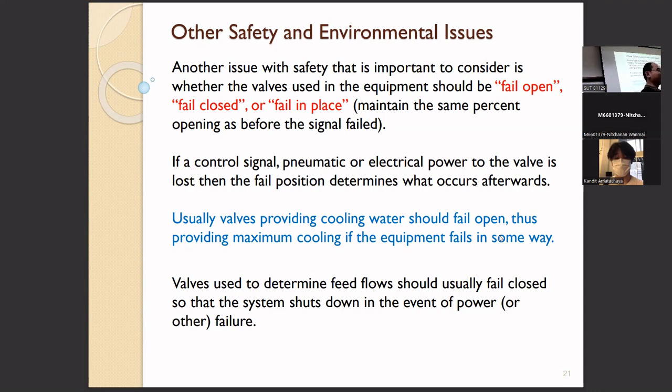It's very important. If you work with gas and you have a reactor or vessel, a closed system, in the closed system a lot of gas is at high pressure. If the pressure is higher than the limit or the capacity of your equipment, there may be an explosion based on the high pressure. But if you connect a safety valve, it will release the gas automatically. That's how it helps you save your equipment.